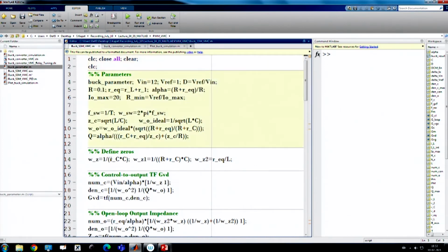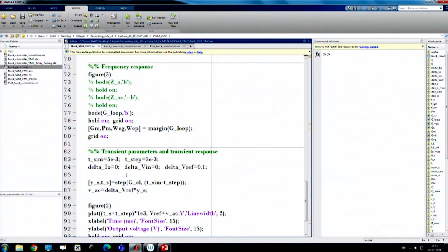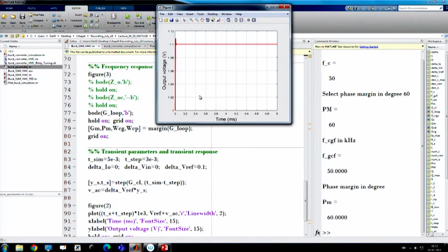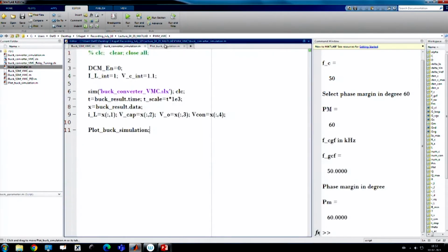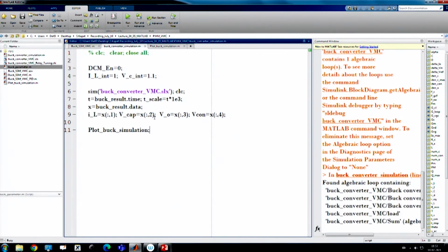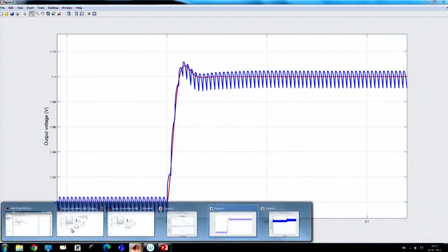Okay. So, it is like a 10 ampere design, or maybe you can design for 20 ampere. So, the first case we are showing is with exact cancellation, and this is the response. We are talking about 50 kilohertz 60 dB phase margin, and if we match with this, this is exact cancellation. So, we want to match the response of the system. This is under highest load current condition and the model is matching quite nicely.